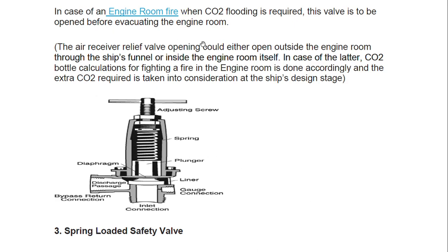In case of an engine room fire, when CO2 flooding is required, this valve is to be opened before evacuating the engine room, because it has fresh air, you can say, which is being stored. The air receiver relief valve opening could either open outside the engine room through the ship's funnel or inside the engine room itself. In case of the latter, CO2 bottle circulation for fighting a fire in the engine room is done accordingly, and the extra CO2 required is taken into consideration at the ship's design stage.